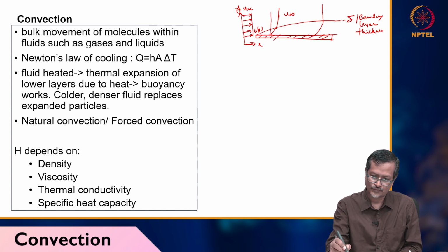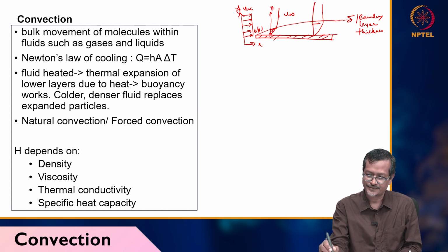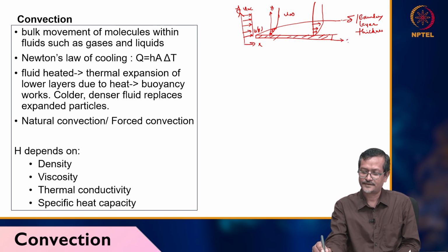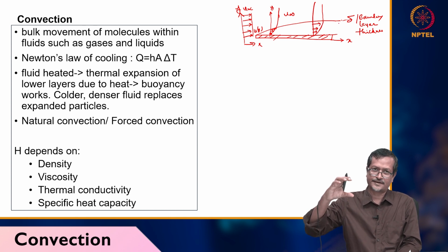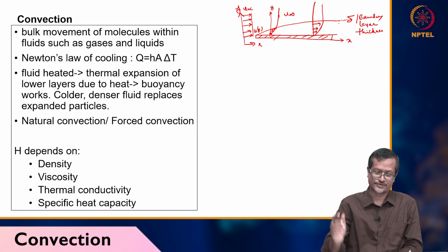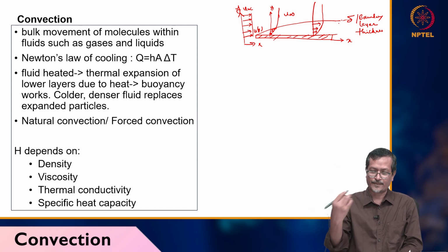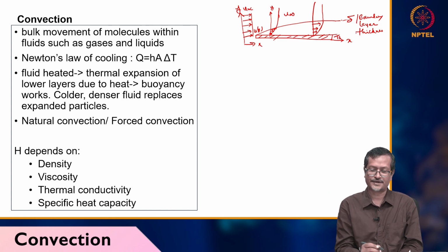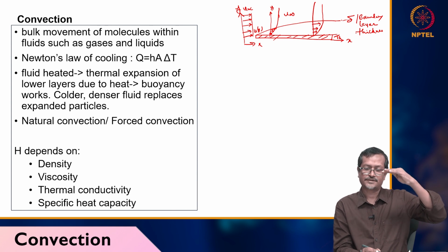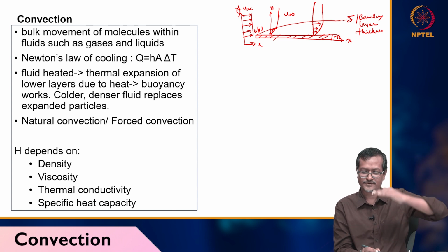Then this is y actually. So my velocity, how it is changing, we'll see. As I am moving from left end to right end, fluid velocity increases and the distance from the layer, the delta, is increasing also. But what is happening if it is heated, like say surface temperature is 100 degrees centigrade and air temperature is 20 degrees centigrade, that means from the surface heat will be transferred to air, because air temperature is lower, surface temperature is higher, and a temperature gradient is created.